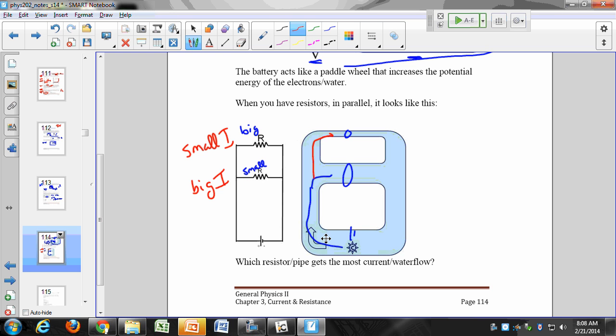Another thing that comes up, if we imagine I have these two currents, I'll introduce this. I have some current here, I, and I'll call this I1, and I'll call this I2. We're going to have a rule that's going to come up in the next chapter, and that is that I is equal to I1 plus I2. That should make intuitive sense to you, right? Because the same is true for fluids: if I have water going through a pipe and it splits into two, I'm not going to lose any of that water. So the sum of the two flows of water going out of the junction will equal the sum going in. So I could write it also as I in equals I out. This is one of our basic tools for electrical circuits. We'll see it again, but it's called the Junction Rule.